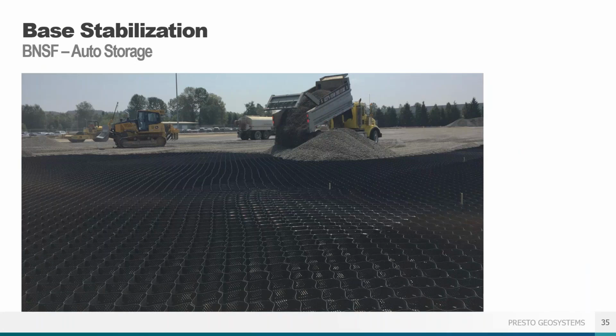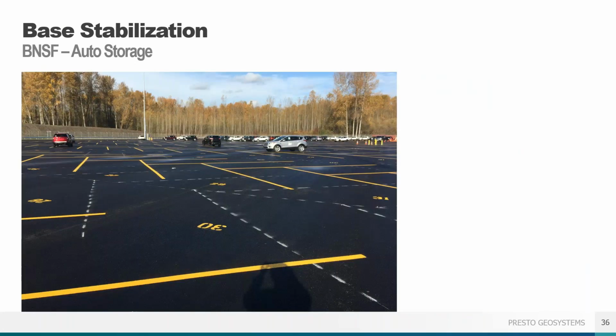You can see the dump trucks back right up to the GEOWEB, dumping the infill material and spreading it with a bulldozer. The material supports loading immediately after filling, no cure time needed, no special weather conditions needed. And again, the material serving as its own site access road for construction. And here's the finished surface.